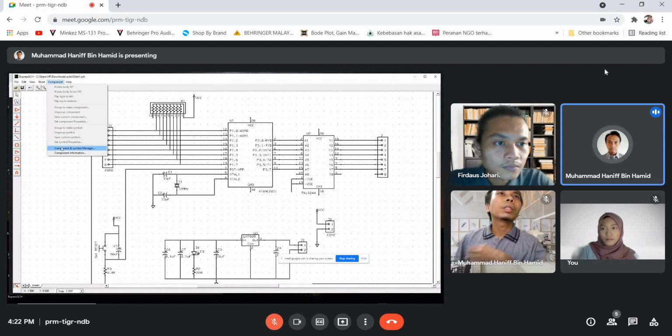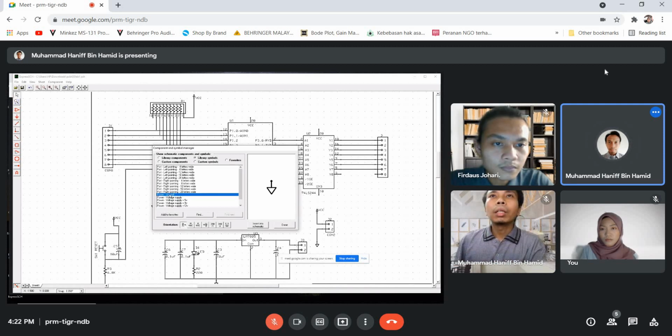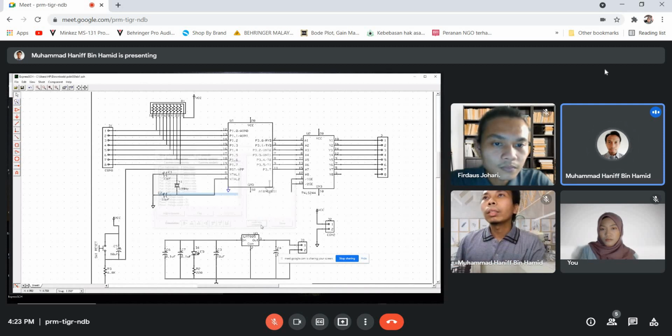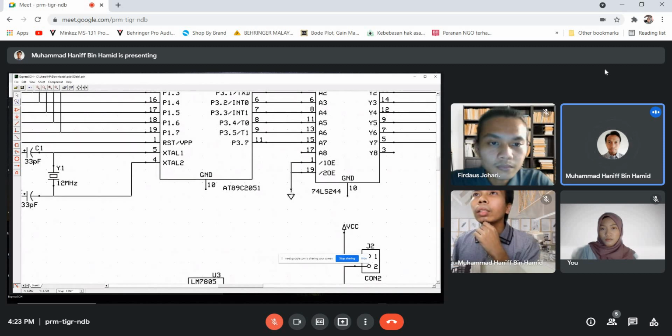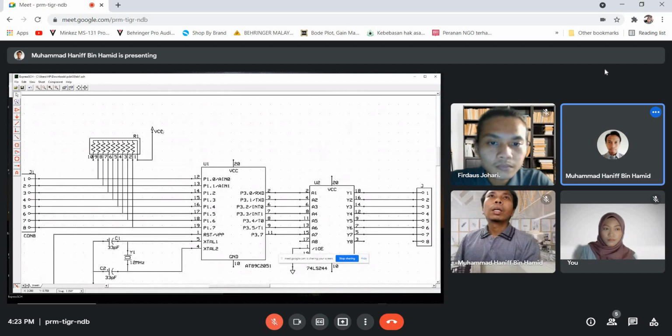So go to component and library, go to library symbol, click ground, set to schematic. So it will be located here in the middle. Change it to your desired location. So here it's already connected. See the symbol is a dot, and the same goes for our supply.